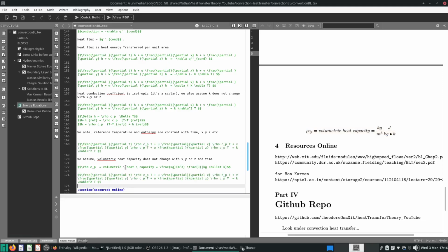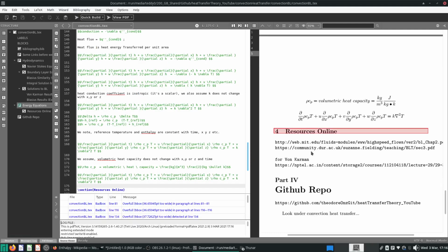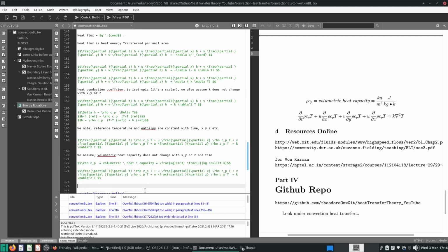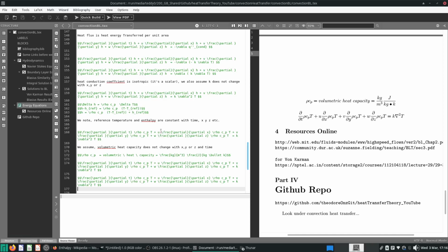It's not always true, yeah. This is a simplifying assumption, because sometimes when the temperature increases, your heat capacity and your density will for sure change. But we are simplifying it a lot for our analysis, so that it makes life easier for ourselves. So if we assume this, we can factorize all of this out and divide through.